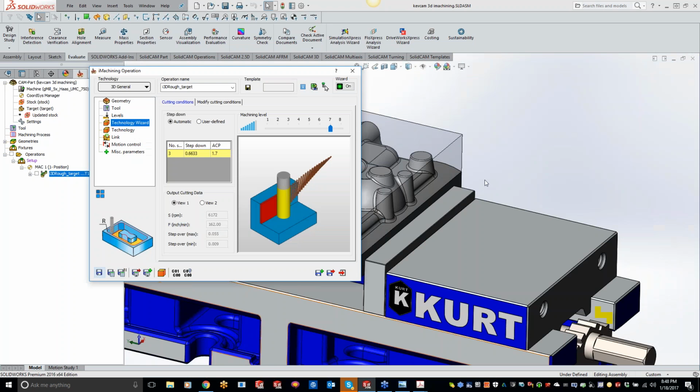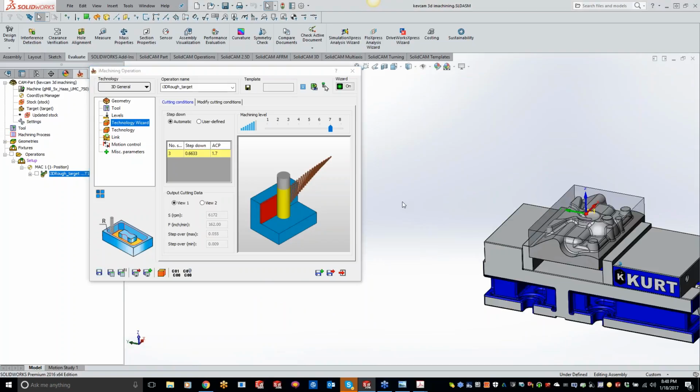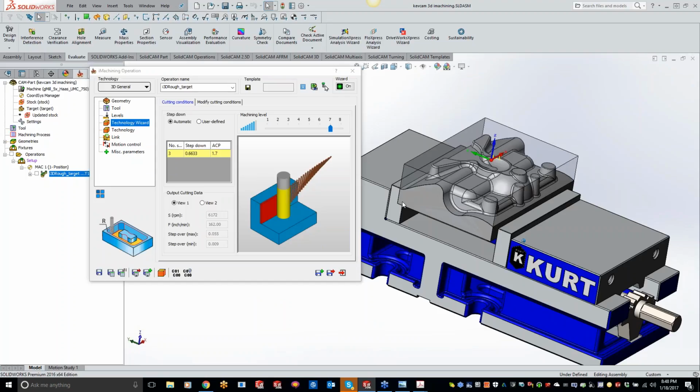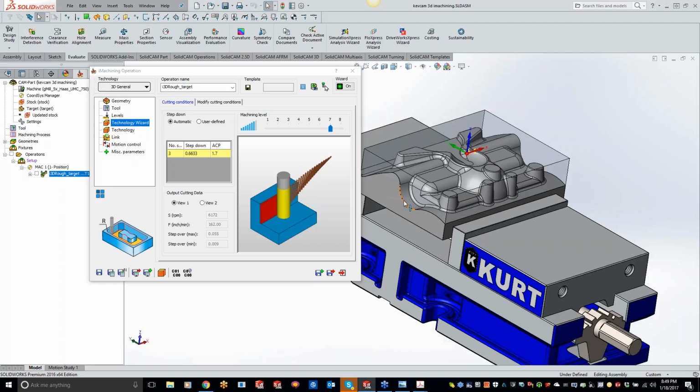Okay, so yeah. Oh no, I was just going to say, I think I kind of understand what you're saying. I mean, basically that distance when Kevin was showing, if you could draw a straight line across that particular scallop, the distance or the depth of that scallop is going to be consistent across the entire surface. Yep. So it really kind of eliminates the need to do a semi-finish or anything like that.